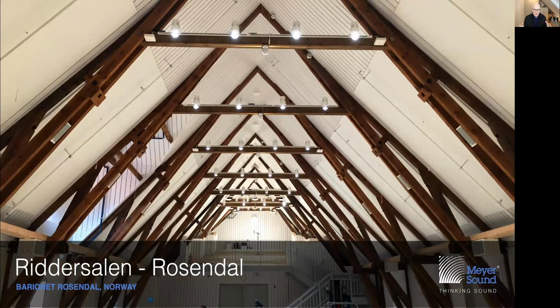And so we had to use Constellation, and they deliberately made the panels in the ceiling as absorbent as possible. Yes, absolutely. The idea being that you kill the first reflection so that the people sitting in the audience aren't aware of the size of the room. And then we simulate a bigger space using Constellation, appropriately delayed, with the loudspeakers delayed. So it worked really well.